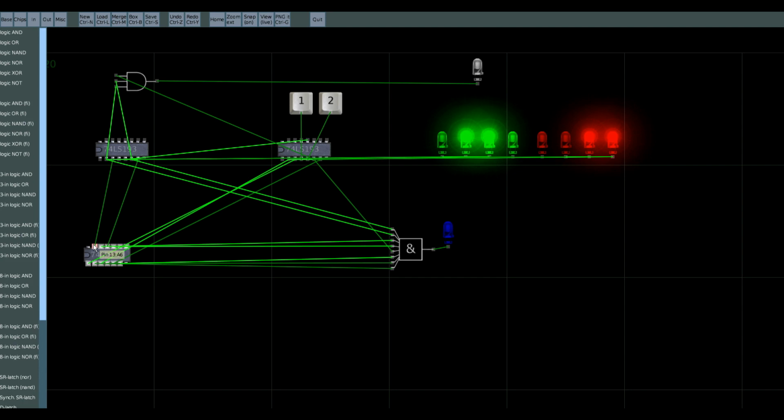So this input, which they call A6, will have an output called Y6, and Y6 is what we're taking through, and what we have here is a standard logic gate, and this is our 8-bit AND gate. So all of these 8 bits have to be on in order to turn this lamp on.